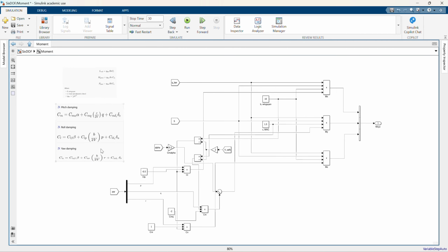So these parameters are going to help us to connect our del E, del A, and del R, as well as our beta. Now, one cool thing to notice here is if you look, the beta is appearing both for roll and yaw, which means beta is the common link between these two, which accounts for the roll-yaw coupling, which is pretty famous in lateral dynamics of airplanes. So let's do this connection first. Let's see, where is CM? Let's take care of the pitch damping since I have only one term to add there. Two were already existing. Pitch damping CM, which I see right there.